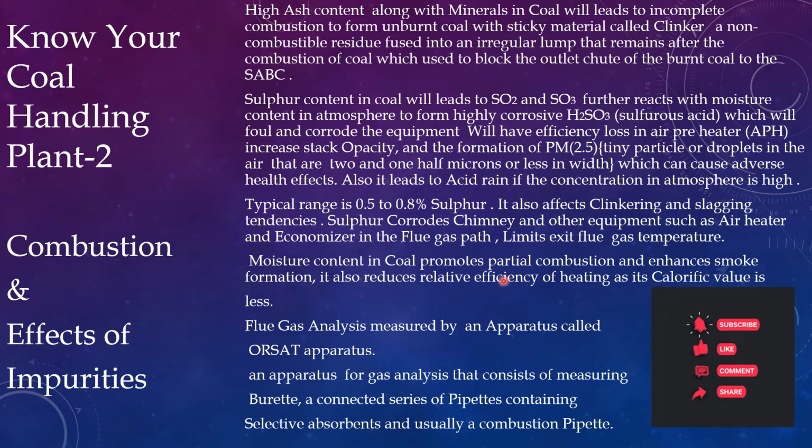Moisture content in coal promotes partial combustion and enhances smoke formation. It also reduces the relative efficiency of heating, and if moisture content is there, the calorific value of the fuel or coal is less. Now we can see about the flue gas analysis.